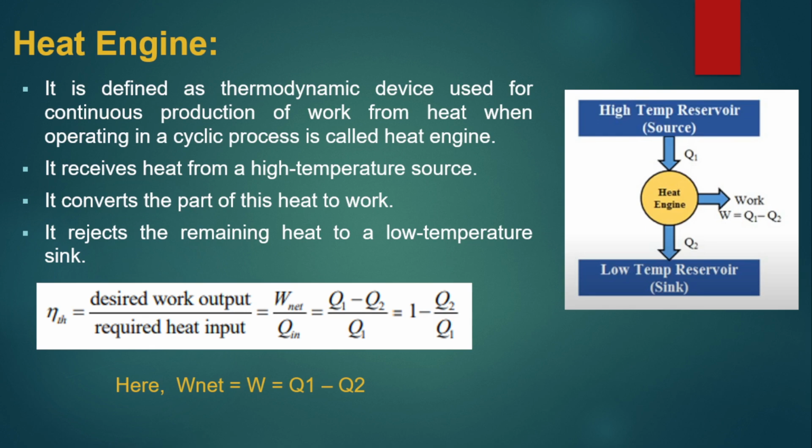The heat engine is a mechanical device. We all know that because it's a part of thermodynamics. It is defined as a thermodynamic device used for continuous production of work from heat when operating in a cycle. It receives heat from the source at higher temperature, and it converts part of the heat into work, where the work is W equal to Q1 minus Q2,